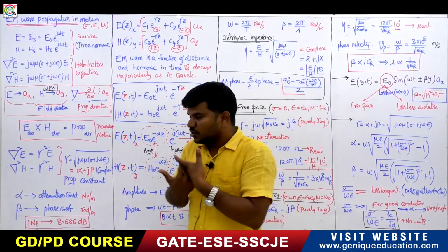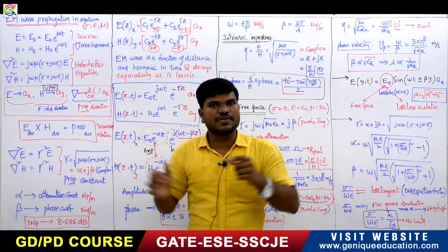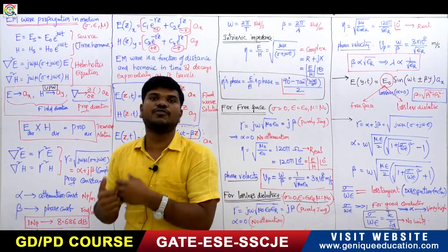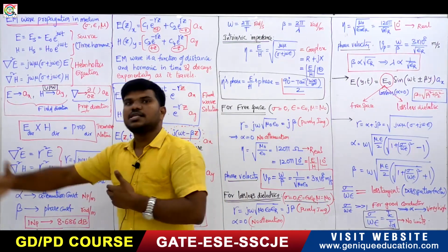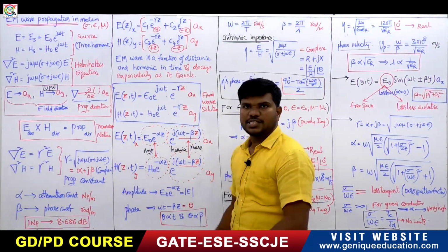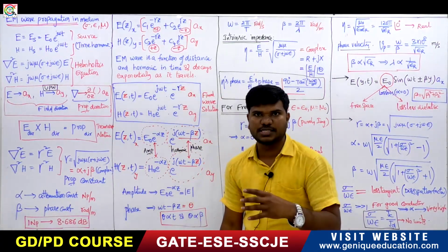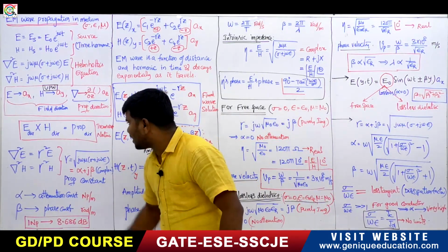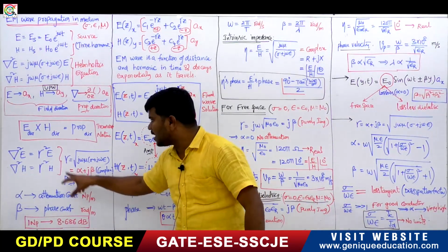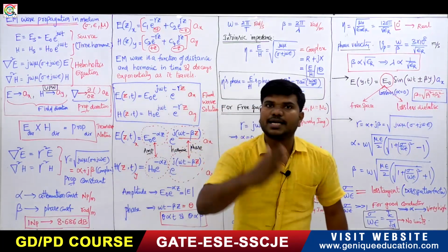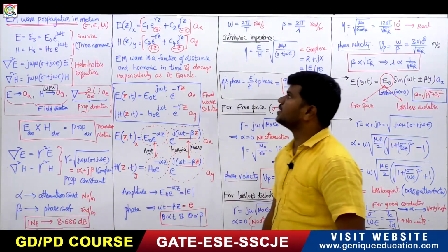It represents how the wave is attenuating, and also how much phase is attained as the wave moves in the direction of space. So this is the meaning of the propagation constant, alpha plus j beta. In general gamma is calculated per unit distance.